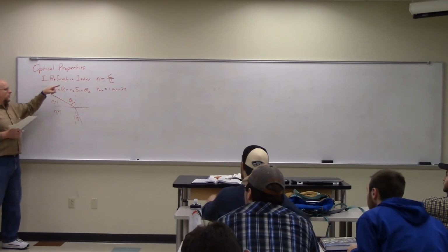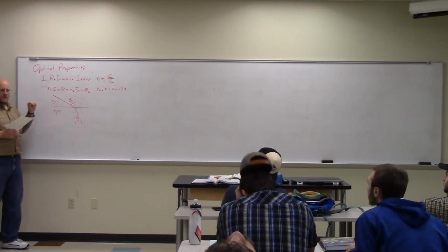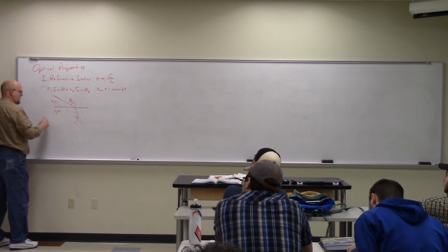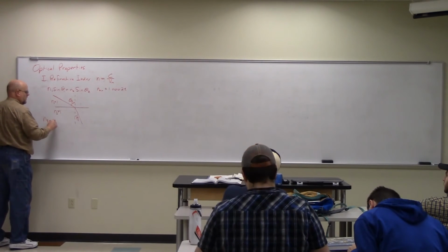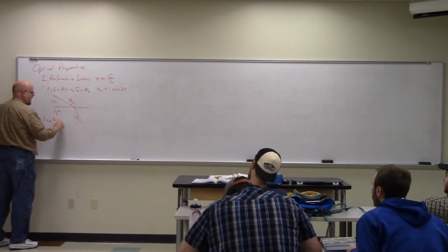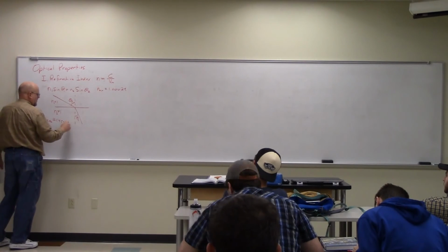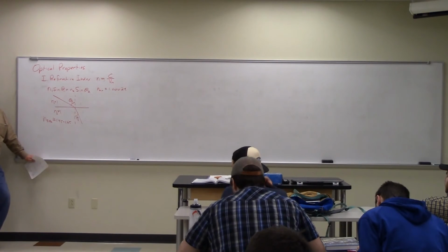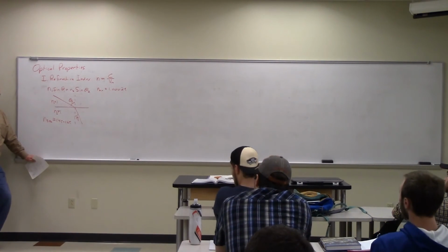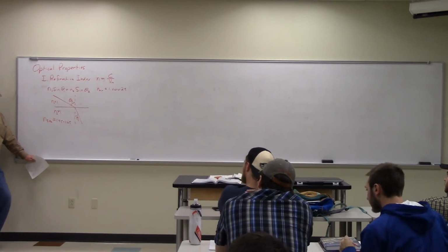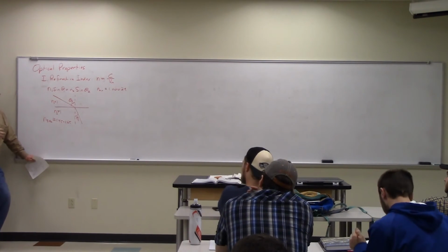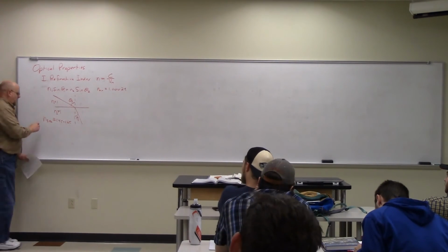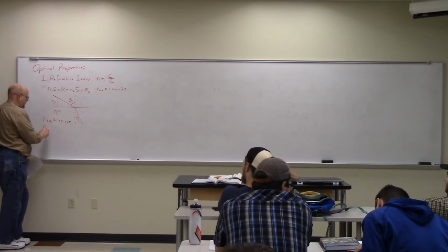Different materials have different velocities and therefore different refractive indices. The refractive index of glass, or of SiO2, is on the order of 1.45 to 1.65, probably on the high end, depending on how you dope it. Pure SiO2 is more on the lines of 1.45, but you can add dopants, some boron, some phosphorus, all those things I mentioned at the beginning, and you can tweak the index of refraction up.